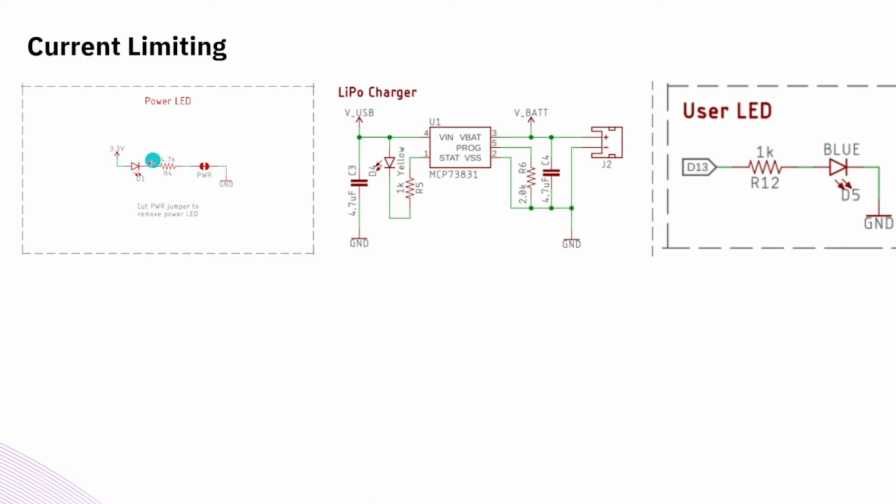Okay, and this resistor is basically limiting the flow of current. So let's say if you use a higher rated resistor, what it will do is dim the LED. Your intensity or lumens of that LED will reduce. And if you are using a lower rating resistor, it will spoil this LED. Okay, so this was all about current limiting.